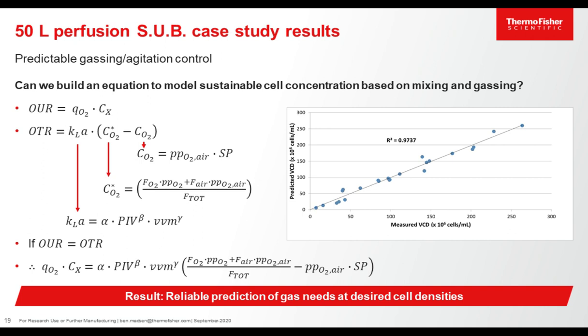Specifically, kLa models have been shown to have strong correlation with power input per volume and gas flow rate in vessel volumes per minute. And if we substitute these equations into our standard OTR equation and then set our OUR equal to OTR, we can create an overall equation to predict the cell density we could support at a given agitation